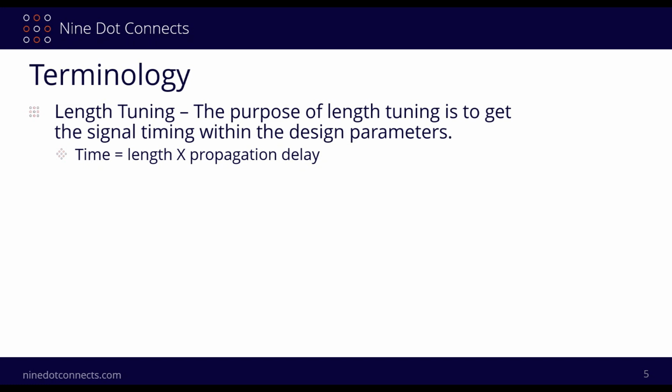And what do you mean by design parameters? It may be a length necessary for a bus protocol, or a length necessary in order to get something to the receiver in a required period of time. We're giving a very general definition here, but the time is the length times the propagation delay. We've done plenty of webinars in the past to talk about propagation delay. That has to do with impedances and the way you set up your boards. But the other element of it, which is what we're going to spend some time on today, is the actual length itself.